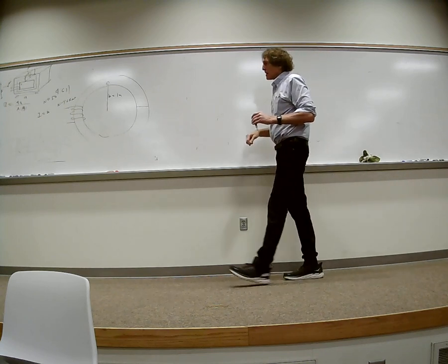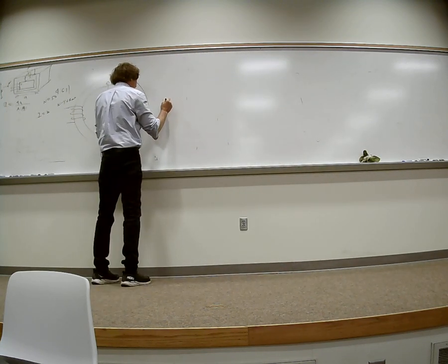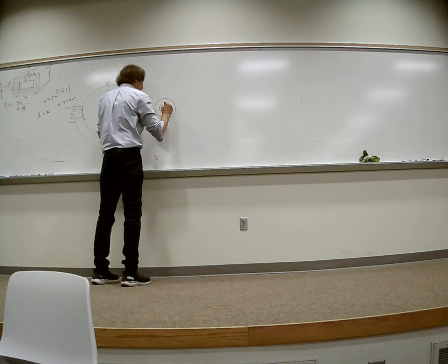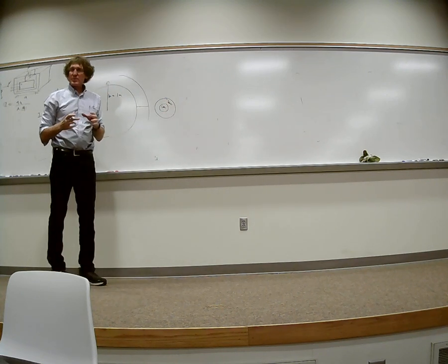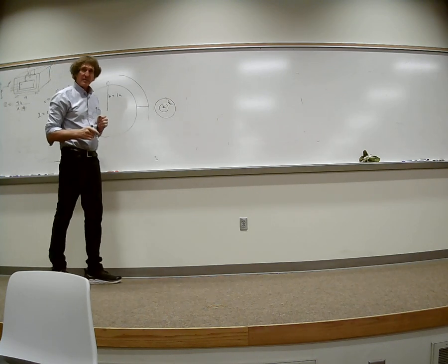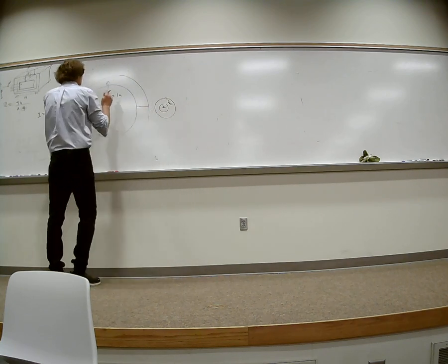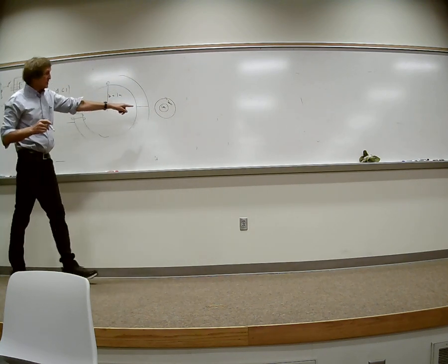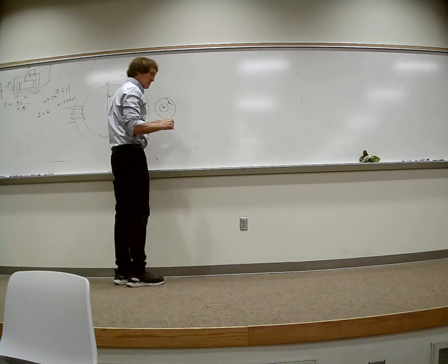All right. Now we come over here to this cross section that I erased. It looks something like this. We have mu relative 1 here and mu relative 2 here. And I forgot the proportional distance. I mean, what's either the area or the radius or diameter of these? The mean radius is 1 meter. Well, that's this, right? But for the cross section, it's a 2 centimeter diameter core with a 1 centimeter thick layer of material on top of it.